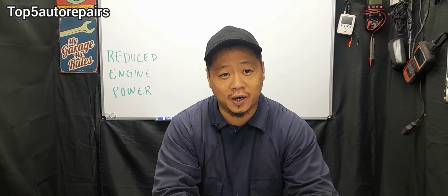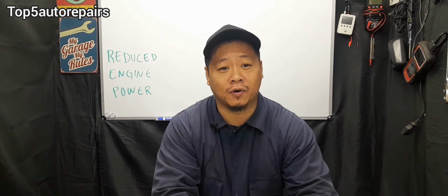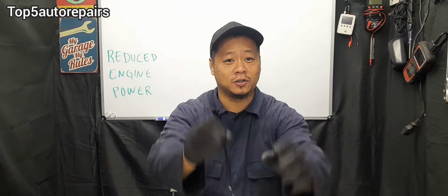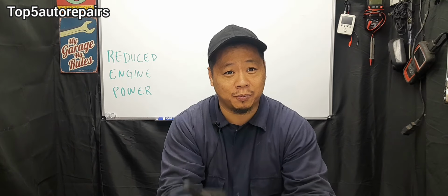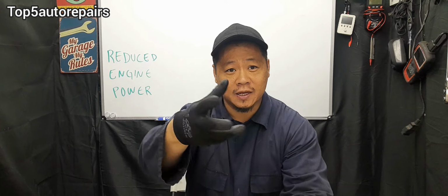And when you look at the throttle body, let's just say for a Chevy Silverado, you're going to see two coolant hoses going to it. So when you're replacing the throttle body, you also need to pinch off the two coolant hoses and replace that throttle body.